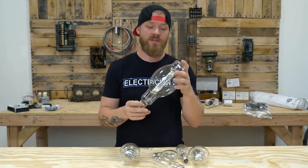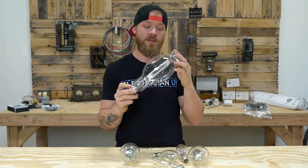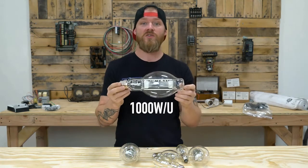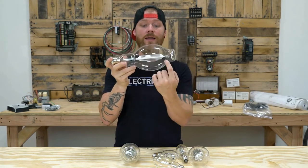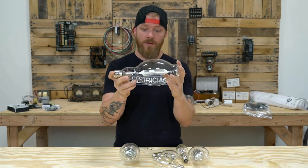Every one of these bulbs is going to have a mounting position. Like this one says 1000 watts / U. U means universal. It means you can mount it upside down, sideways, upward, it doesn't matter. The arc is going to act the same way in that tube regardless of how the lamp is mounted.